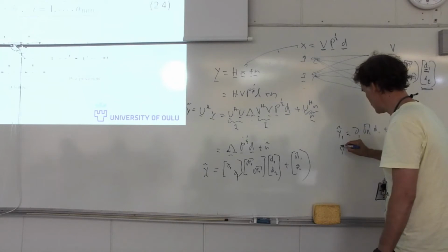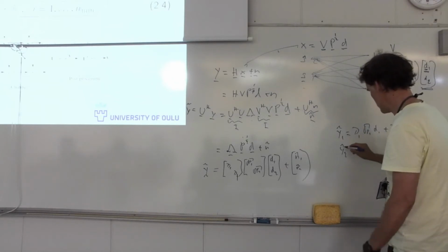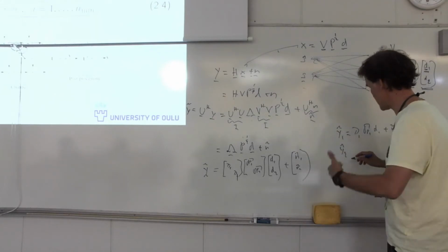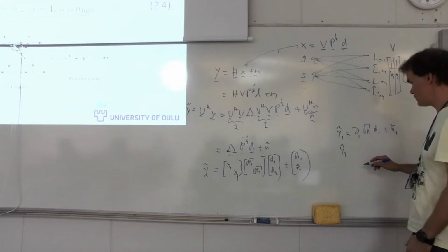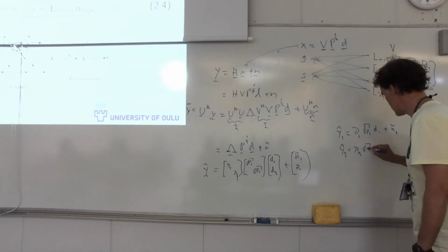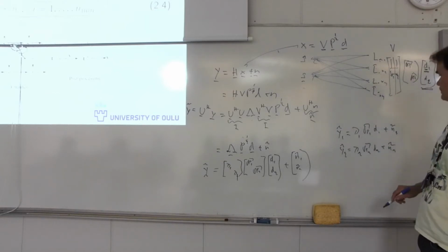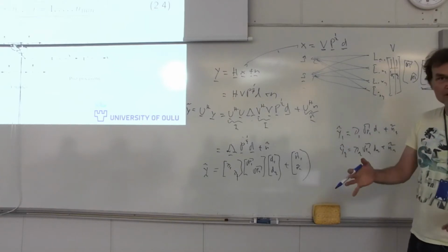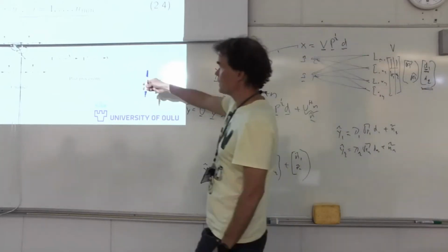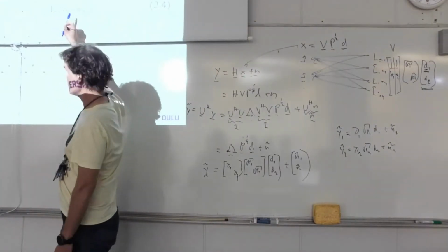And for stream 2, the equivalent received signal at the output of the receive beamformer U is lambda 2 square root of P2 d2 plus n2 tilde. Okay, so these are two parallel channels. You can see that we have min, which is 2 in this case, parallel channels.